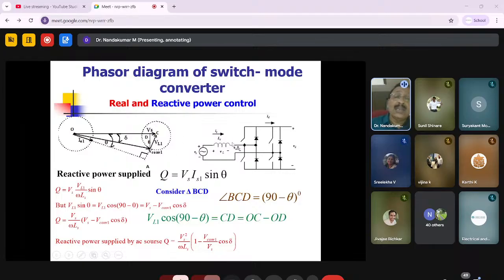That is basically you are controlling the converter, both magnitude and phase angle, or another way you can say that you are controlling the voltage across the linking inductor, because that will decide the magnitude of the source current as well as the phase angle of the source current. As VL changes in magnitude, ISN also changes, both the magnitude as well as the phase angle of this source current. Of course, the source voltage you don't have any control over. This is fixed. You can control only the magnitude of the source current as well as the phase angle of the source current.